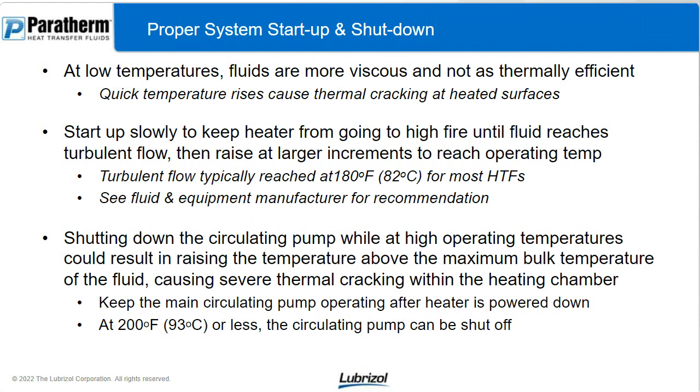But once the system is filled properly, following the procedures from the equipment manufacturer and the fluid manufacturer, you want to make sure you start up properly. When fluids are colder, they have higher viscosity, which means that they're going to stick to the walls of the pipe more. It means they're going to stick to the heated surfaces and break down faster on the pipe walls. So a low temperature, more viscous fluid is not thermally efficient. If you put a lot of heat energy onto that cold fluid right away, you're going to shock the fluid basically and crack the fluid onto the heated surfaces.